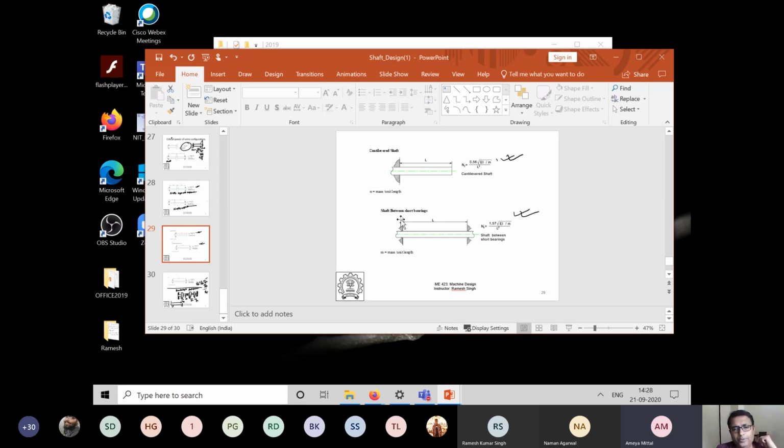So it's like a fixed support. That's all I was saying, that we are using the concepts of beam theory to model these shafts to get the natural frequencies. And Dunkerley's method says that you can assume that each of them is independent and just sum it up, so basically 1 over omega squared. So it's an inverse of square.